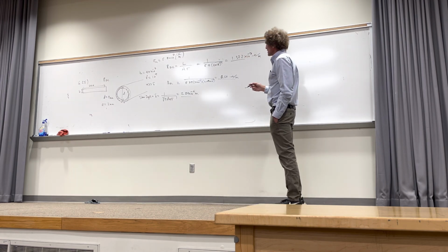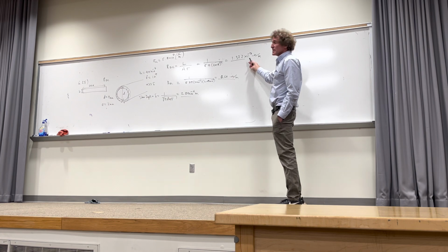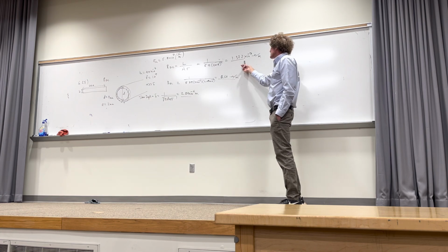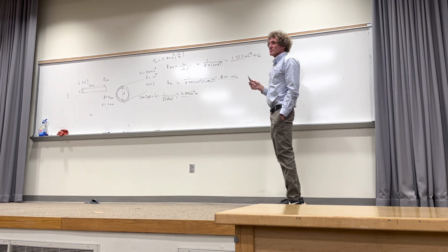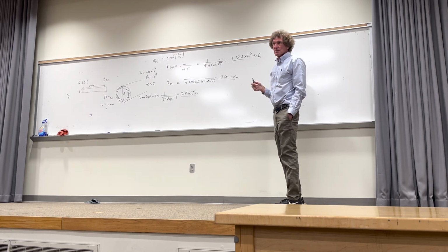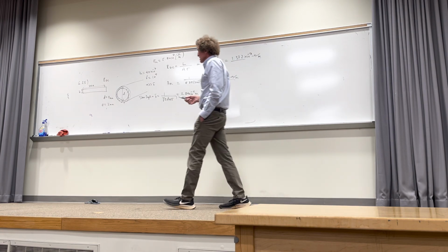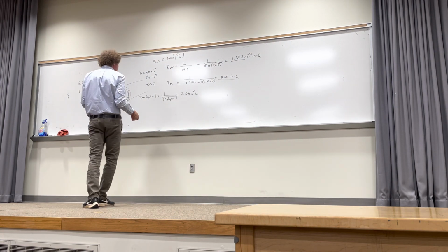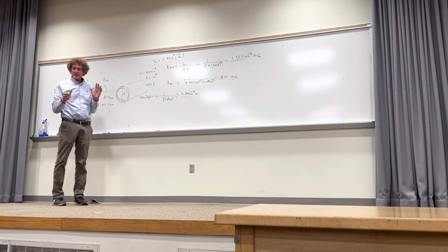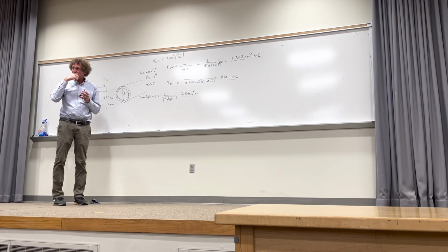And you can see it's significantly higher than this. This is 660 milliohms per meter. This is 1.372 milliohms. And the reason is the area is now much less that the current flows in. And then the limit, you can see here, as frequency tends to infinity, the skin depth goes to zero, so the area goes to zero and the resistance goes to infinity. Y'all follow me on that, class? Just to be aware of that thing.